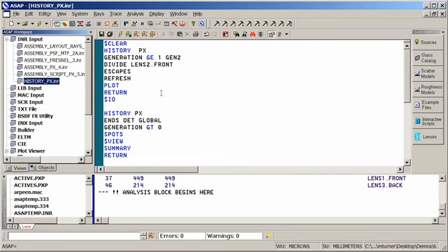This is an example of Path Explorer commands within ASAP. This first set of commands is for the previous example where we looked at the Fresnel reflections off the front surface of the second optical component. What we want to look at now is all of the rays that ended on the detector that were not of the original ray bundle. So I've eliminated the 0th generation, and we're going to look at the rays that otherwise end on the detector. But rather than looking at the rays, we're going to look at the spot information. Where are the rays on the surface? We could also look at some summary statistics as well.